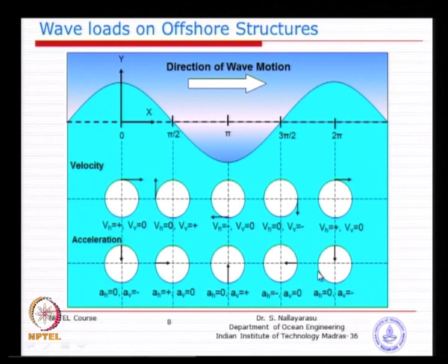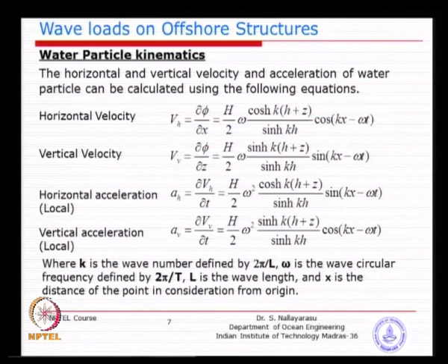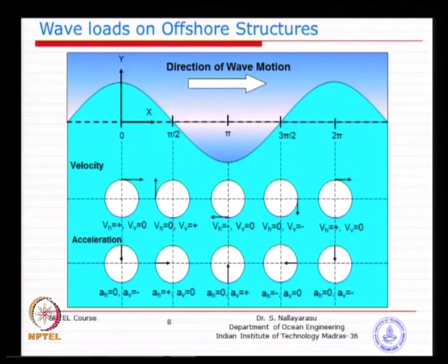In order to do that you should understand how the wave propagation is going. This picture will give you a clear idea that there is always an out-of-phase relationship, just because you are differentiating the velocity potential once for velocity and a second time with respect to time for acceleration. You could find this picture in the textbook also, but only the understanding of what is happening at which phase is required.